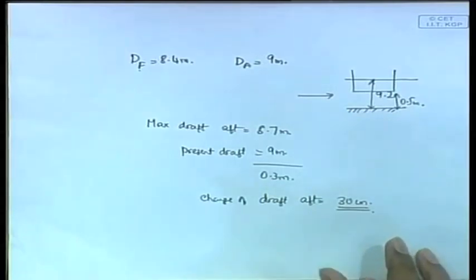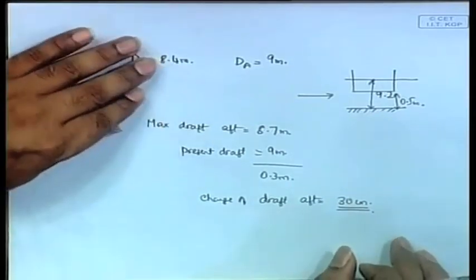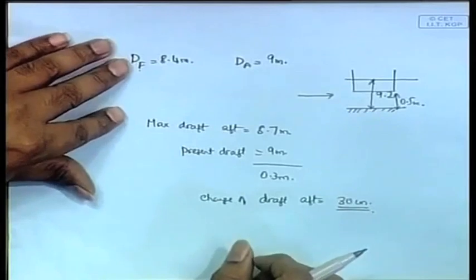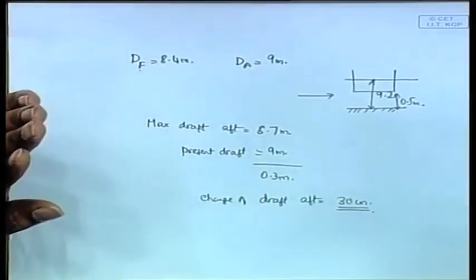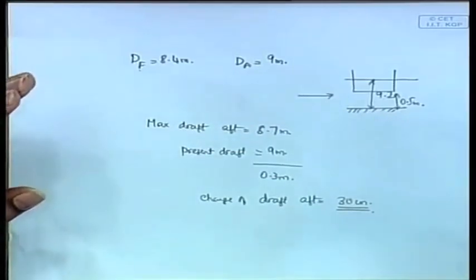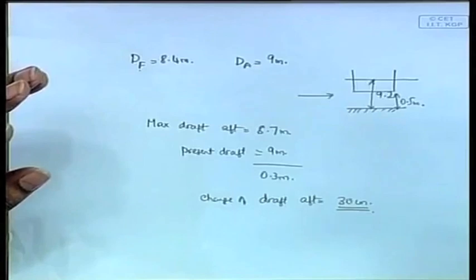Now, this is another thing you should take care of. The problem finally comes down to finding what is the weight transferred or weight discharged and what is the distance. There can be two possibilities. First, you are discharging a weight, meaning the weight is removed from the ship itself, not moving inside the ship. When you do that also, you will need to find out the position at which that weight is taken out. You will need the LCG for that. We will see why it is required, but you need that to find some moments.